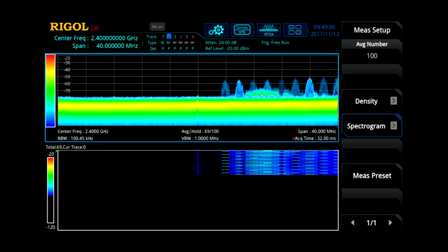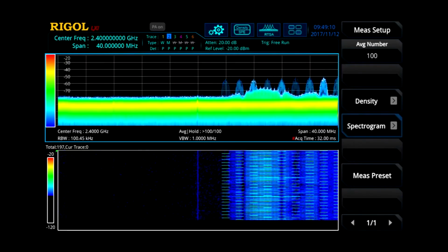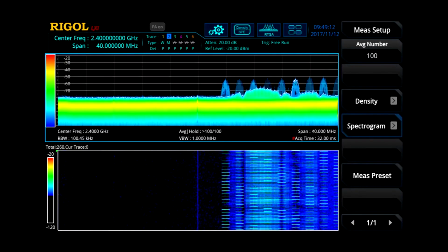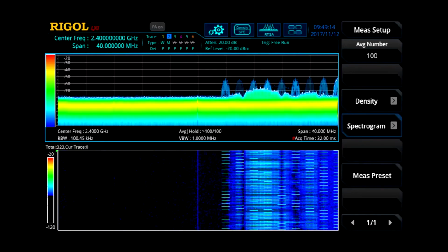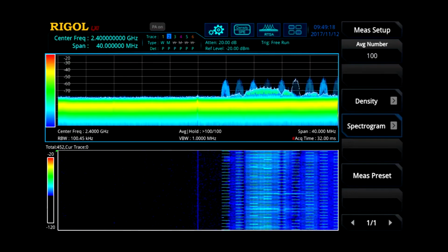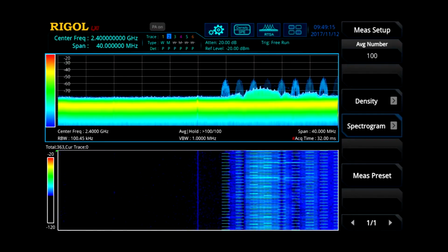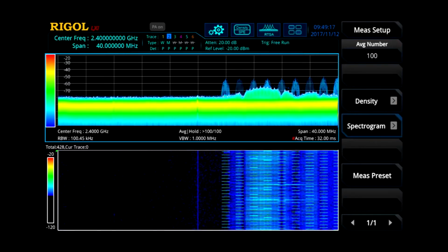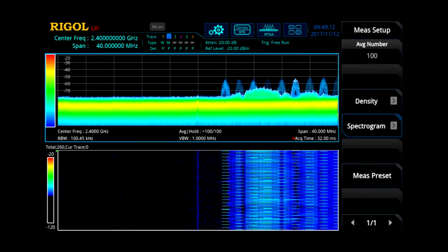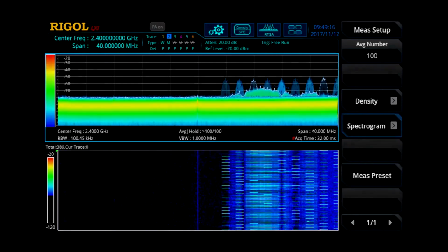Real-time spectrum analyzers call the ability to capture short-duration transient signals the 100% POI, or probability of intercept. It is measured in time and indicates the shortest signal that is guaranteed to be captured. The RSA 5000 can be set for 100% POI as short as 7.45 microseconds. This is accomplished by the calculation of more than 145,000 FFTs every second within the instrument.